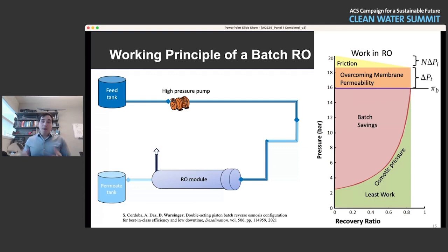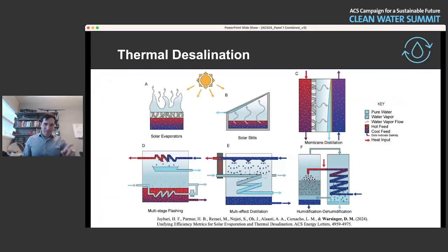Next up, membrane distillation. I'm still going through these. Membrane distillation, see here, is an emerging technology. It essentially resembles a counterflow balanced heat exchanger with water being preheated on the right side, going through a top heating, and then going down and then it crosses the membrane and evaporates and recondenses. By having it as a heat exchanger design, you can get good thermal performance and good inherent energy recovery while having one very simple device.